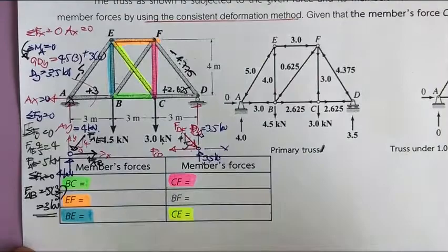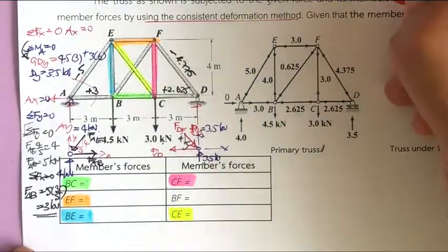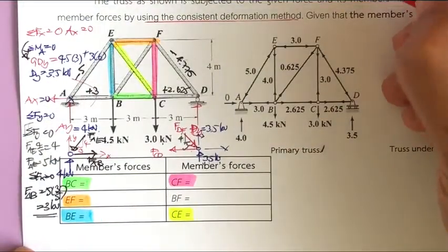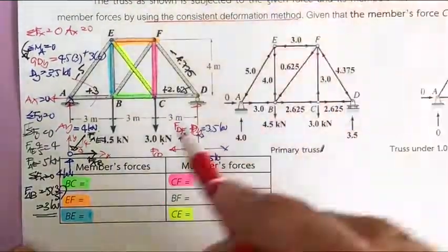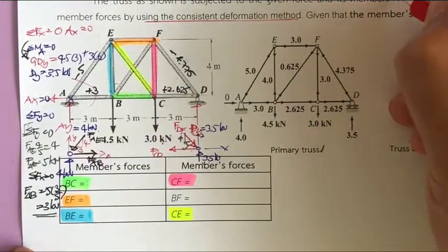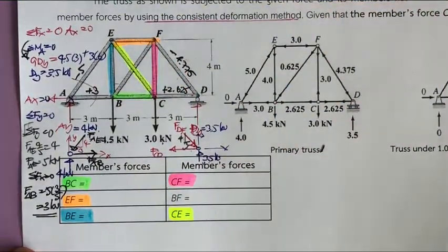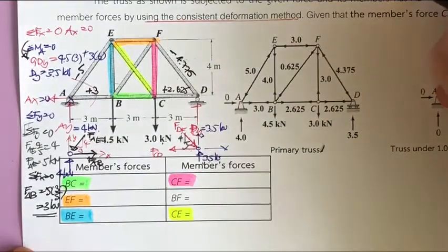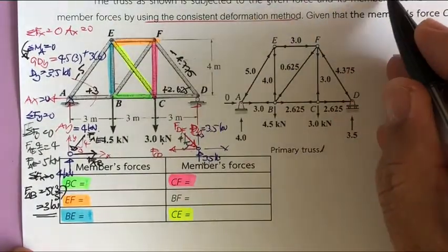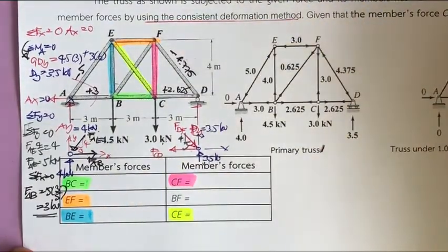And you got to compare with the equation you have. You have two equations per joint, and times the number of joints. So it's 2 times 1, 2, 3, 4, 5, 6 times 6. That is going to be 12. So the degree of indeterminacy, which is DOI, is going to be 13 minus 12.